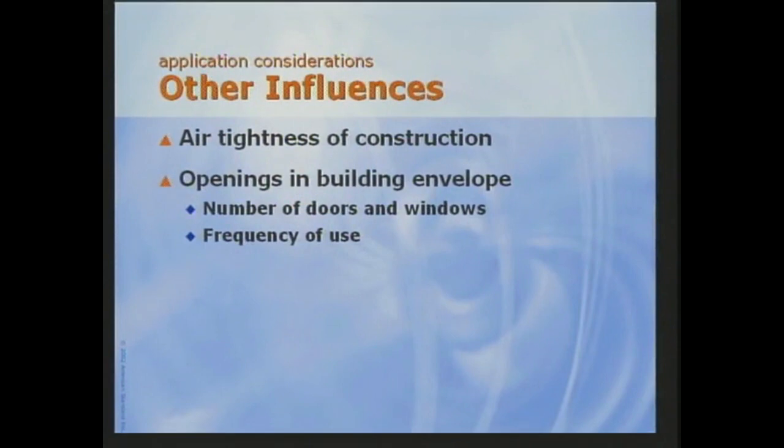Second, windows and doors. Many windows means many cracks to seal, and operable windows left open act like large holes in the envelope. Improper window installation can cause building leaks. Doors that connect directly outside become a hole in the envelope when they're open, and they pump air as they open and close.